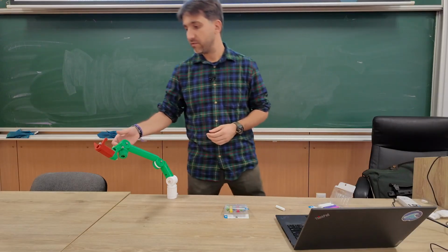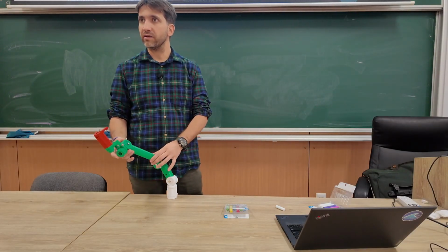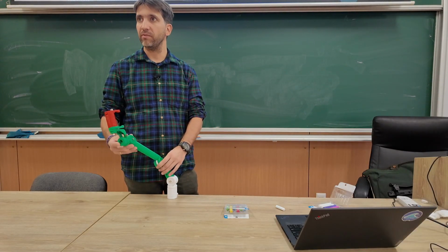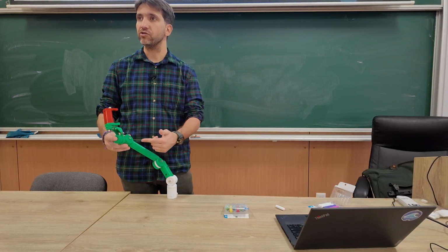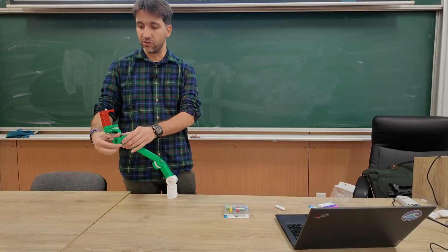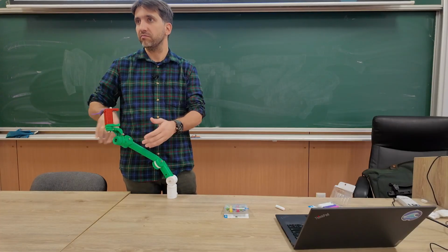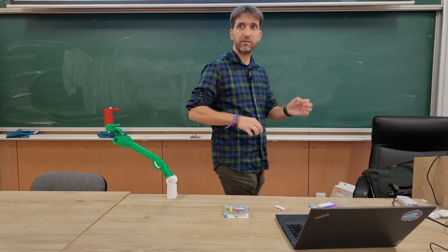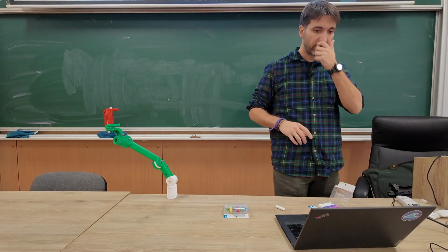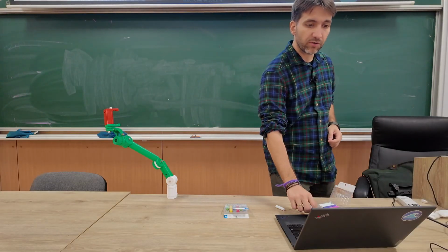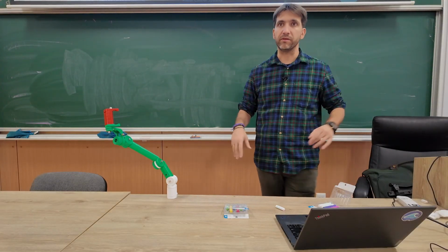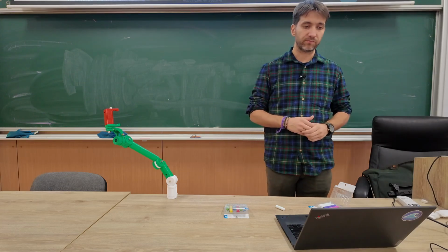Yeah, so basically I have independent control of each joint, right? I can modulate the torque for each joint independently, correct? So I can send different voltages or different currents to each joint. So that's not an issue, because they are physically different entities, and a little wire goes to each one of them, right? And at the same time, I also have different encoders on each joint, so I can measure Q1 and Q2 separately. Right, so that's not an issue.